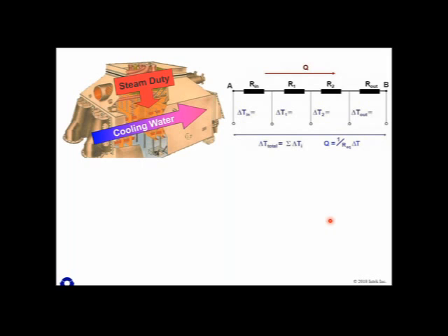Now I'm going to show you an illustration of the thermal impedances that exist on tubes in the condenser, with the goal of showing you from a heat transfer fundamentals point of view how condenser pressure increases in the condenser. I know this is very basic, but understanding the temperatures and heat transfer layers lays a foundation for understanding root cause for real-life problems like tube scaling, condenser air binding, imbalances in air offtake flow rates. All very practical issues come from understanding this type of stuff.